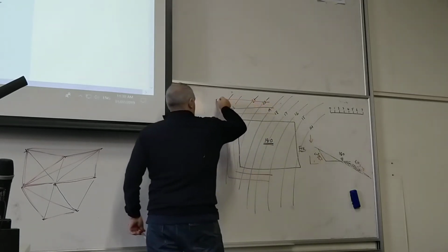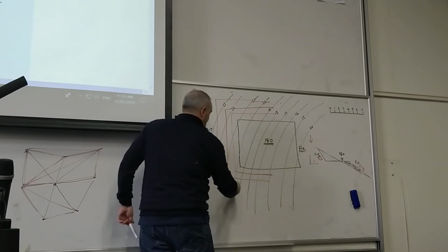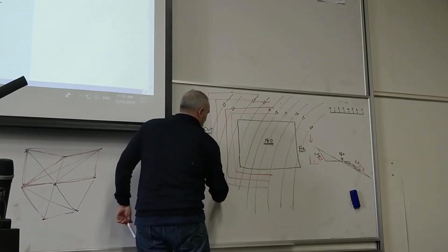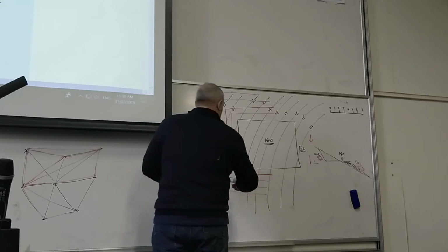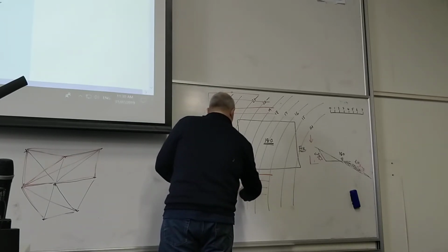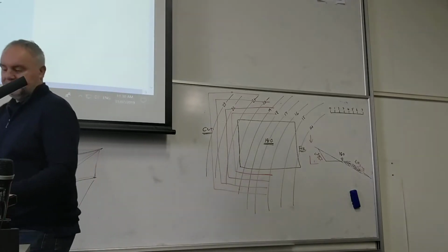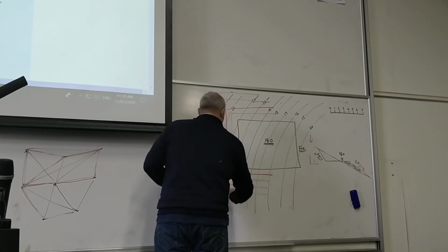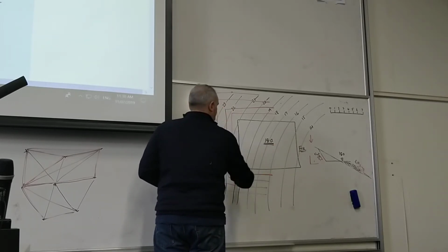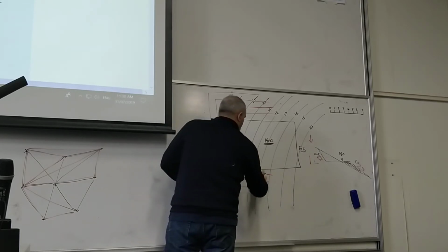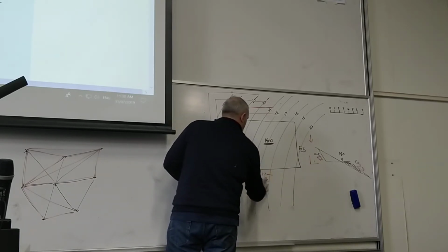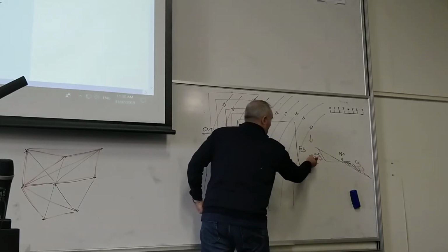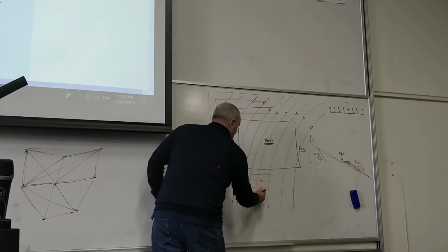So let's come around here and do 1 metre, 1 metre, and 1 metre. So in plan view, we've gone off 1 metre, but we've also gone up in height by 1 metre as well. So if this platform's 18, this one here is going to be 19, 20, 21, because we've gone along one and up one, along one and up one. 22.